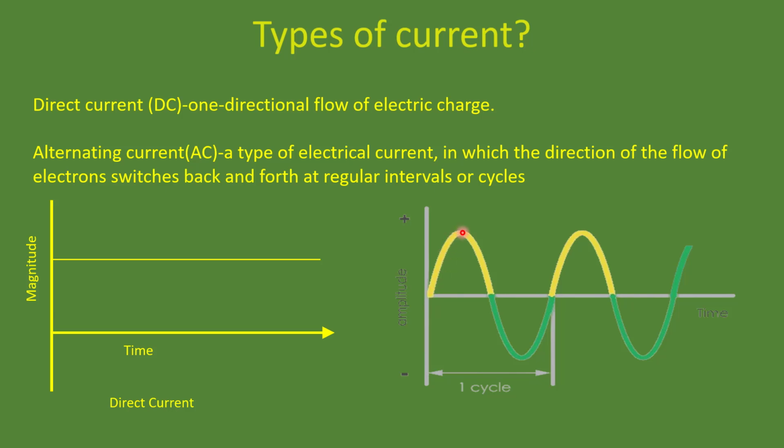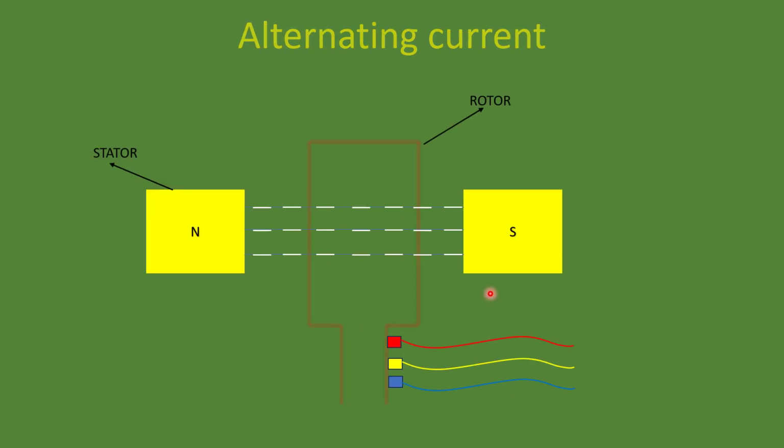Here, the coil is parallel to the magnetic field. After the coil moves from the parallel position, the induced EMF decreases and goes back to 0. In this position, the coil is again perpendicular to the magnetic field. Then the coil starts to rotate in another direction.